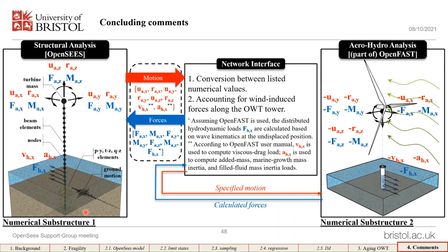Yeah. Because multi-support excitation doesn't make sense in this case because the loading is applied entirely along the fixed end support, right? It's just being applied for fixed nodes. Oh, for all the fixed nodes, which represent the soil. Okay. Yeah. So then it's technically uniform excitation then.